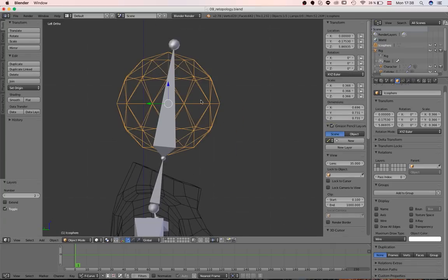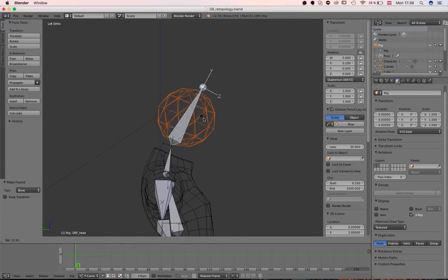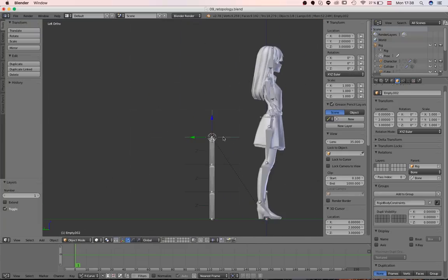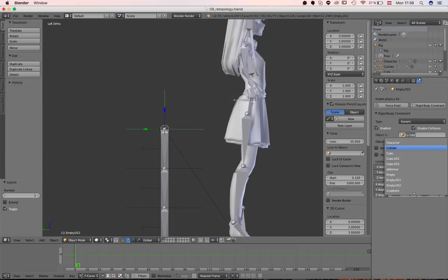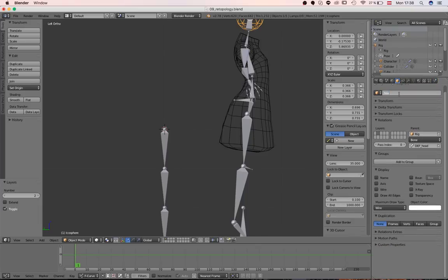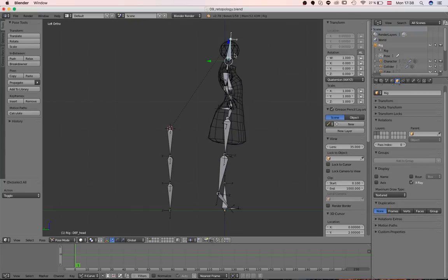I just select the sphere and then the head bone and parent the object to the bone, so that they just move together. And to fix the final problem here, just go ahead and change the first object from collider to our new icosphere. I guess that's what it was. Let's rename that, by the way, to head collider. Great. So now if we animate the head again,